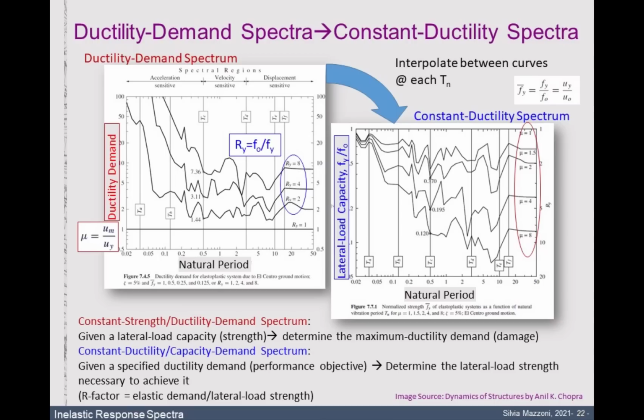Now, because typically in design, especially when you relate it to displacement-based design, but even at performance levels, right? When you think about a ductility of 8, then you know that something is about to collapse. Lower ductility levels, you can almost relate to different performance levels. So you want something to remain almost elastic. So maybe you want to design your structure to reach a ductility level of 1.5. If you have reinforced concrete columns, it's just a bridge, maybe you're fine with going to higher ductility levels.